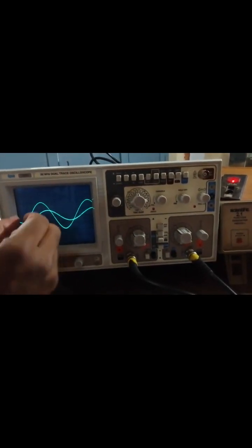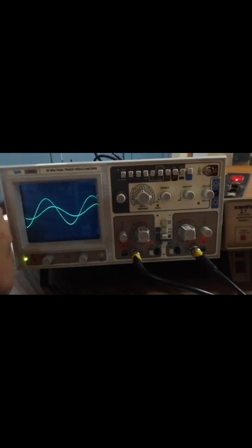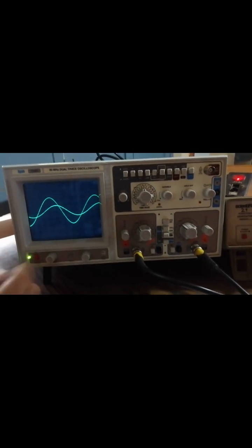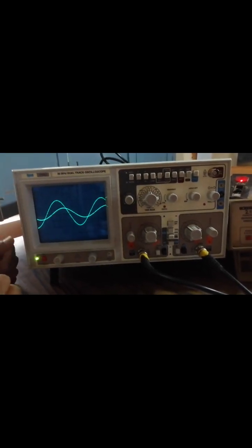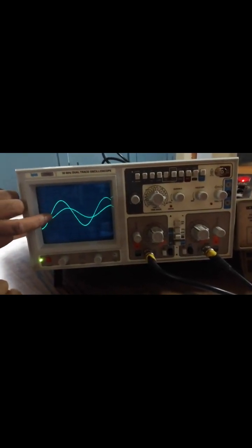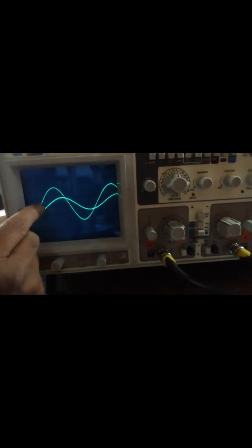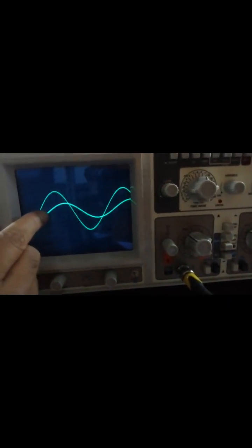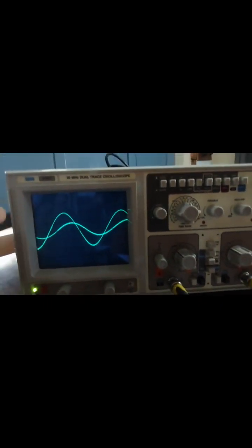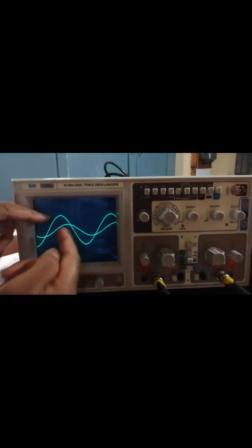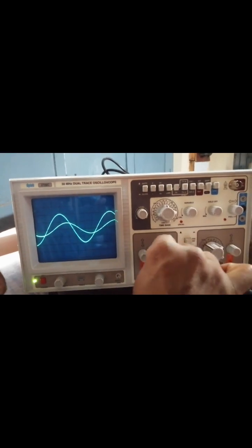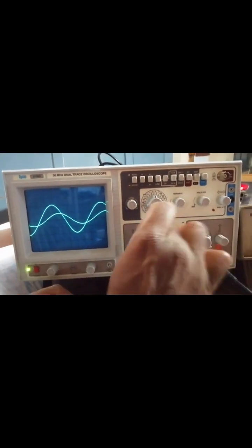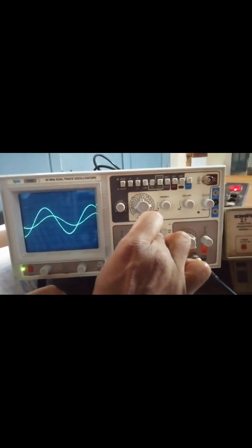What is happening when you move from 1 to 0.5? Of course, the gap between these is getting expanded, but at the same time these lines are going to get inclined more. Obviously you will get confused whether it is passing through a point 0.2 or 0.3, something like that. If you want to measure it accurately, you should make these two curves more and more steeper, and for that you change the multiplication factor of the amplitude knobs.